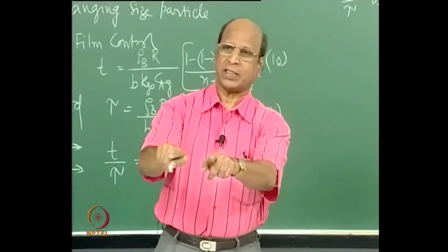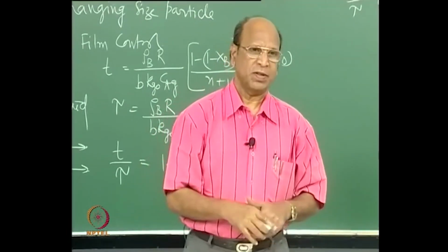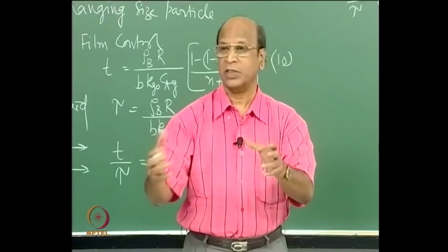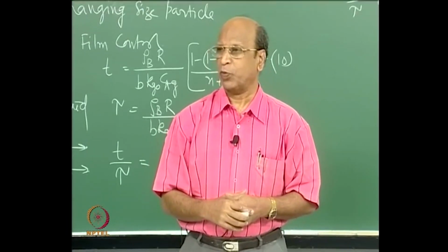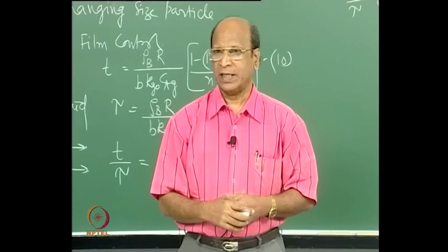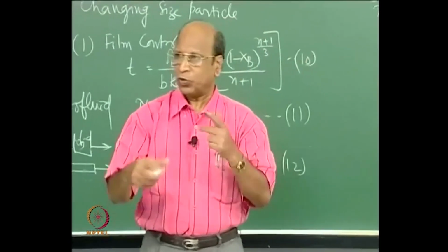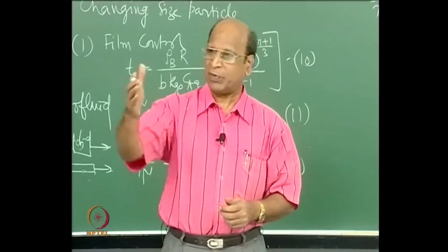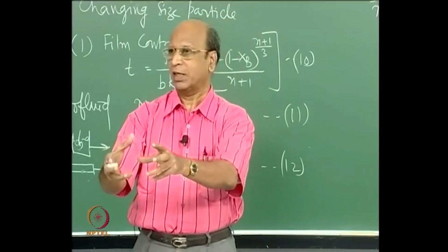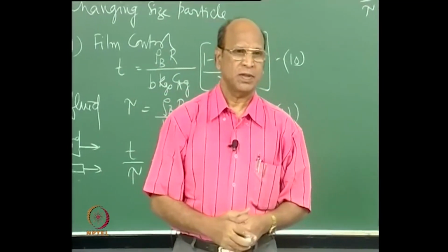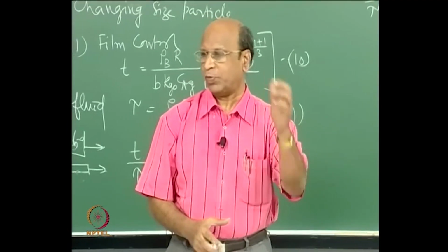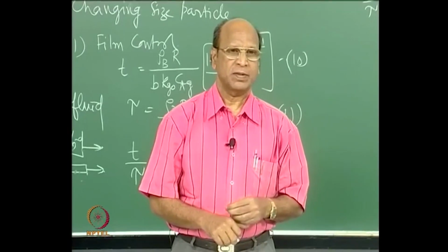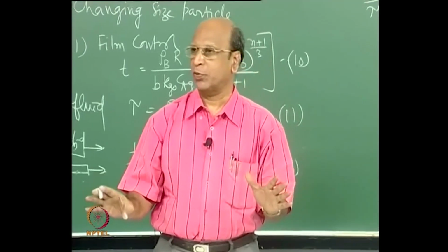But if I give you this equation and then ask what the contacting pattern is, you can generate an infinite number of possibilities. This is again a wonderful point you have to remember; we discussed it last semester. You understood the question, no? Given a reactor, you know definitely what the RTD is, but given an RTD function, an RTD equation, you can never say what kind of reactor you have. There is only one possibility, one condition: if you have plug flow, a direct delta function, no other system can give you a direct delta function.